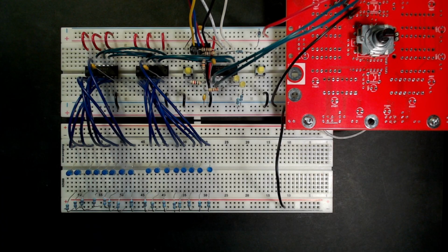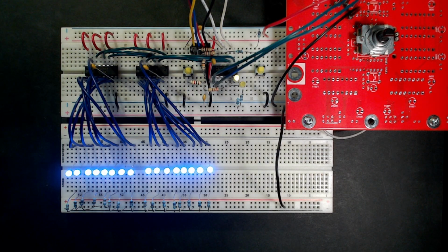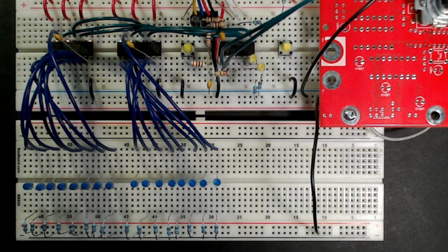nothing to clear it. In fact, even on startup, if I cut the power and then bring the power back on, you'll notice that the indicators sometimes are lit entirely and sometimes not lit at all. That's because when we cycle the power to the shift registers, the value that's currently sitting in the shift register is, well, random. We can't determine it unless we reset it.